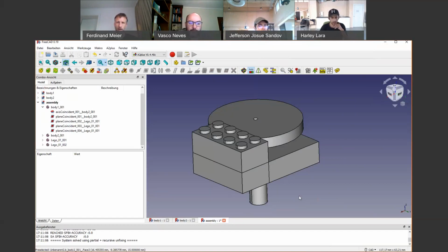And then in Inkscape, this depends a little bit on which laser you're using. For our Epilog laser, any line that is thicker than 0.025 millimeters is going to get engraved, and anything thinner is going to be a cut. Okay. I think on Daniele's laser, he's using VisiCut now.